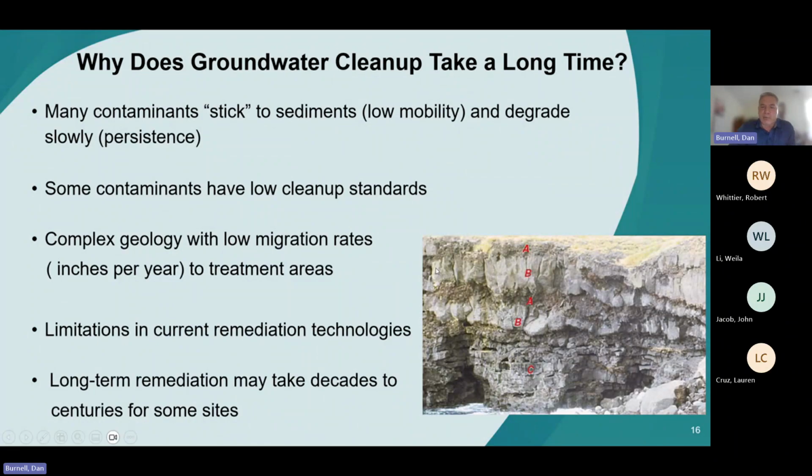And if you recall, for example, the volcanic layers form from different lava flows over time. And this picture we looked at before, this is a cliff. And so we had these higher permeability zones, and then we also had the more massive zones. And so as contaminants, if we're, for example, put down deeper, these layers also occur like this. And so typically we're going to pump the groundwater from the more permeable zones where we can get water out.